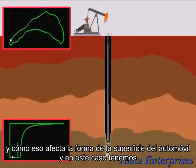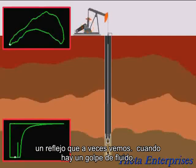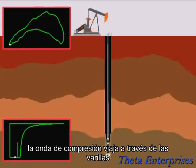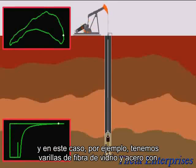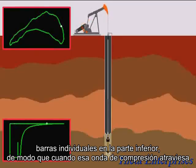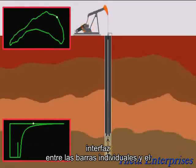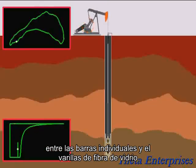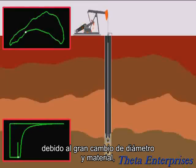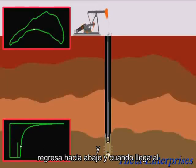In this case, we have a reflection that we sometimes see when there is fluid pound. The compressive wave travels through the rods. In this case, for example, we have fiberglass and steel rods with sinker bars on the bottom. So when that compressive wave goes through the sinker bars and hits the interface between the sinker bars and the fiberglass rods, because of the large change in diameter and material, a lot of that energy gets bounced off and goes back down.